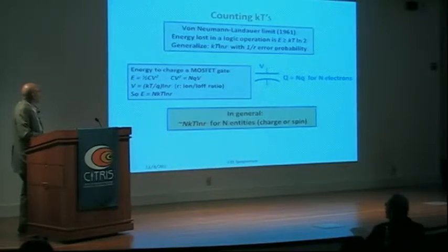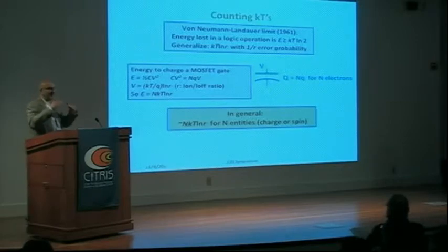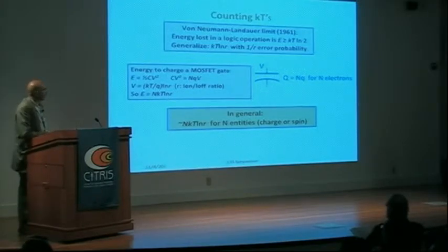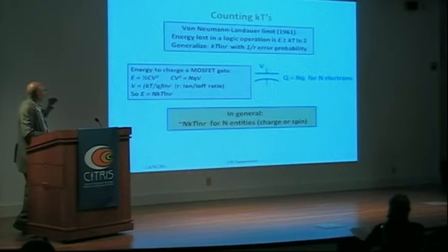And of course, now what about TFETs, you ask? How does that help? If we can increase the subthreshold slope, we somehow seem to beat this number down, and that is true and consistent with this argument. And one of the interesting things about TFETs, and I think this point was made in a couple of the talks yesterday, is that by squeezing the band edges together with the density of states switch, there's an effective clipping or filtering of the Boltzmann energy distribution, the thermal tail.